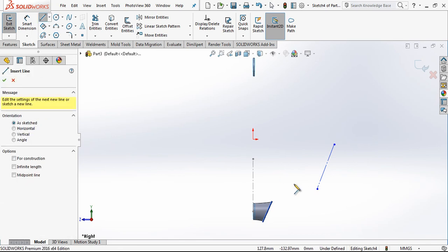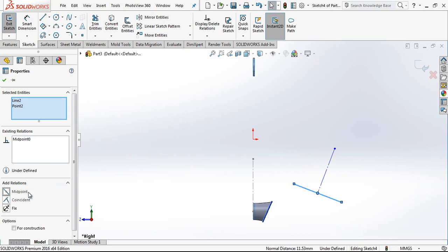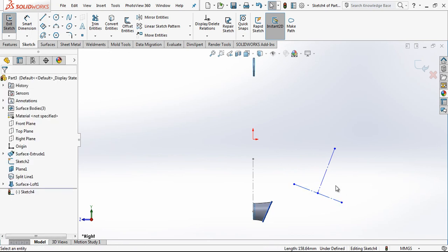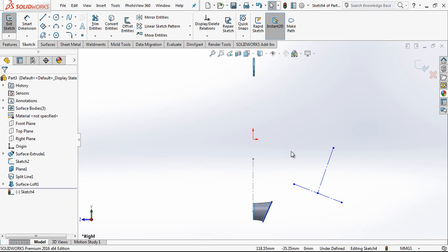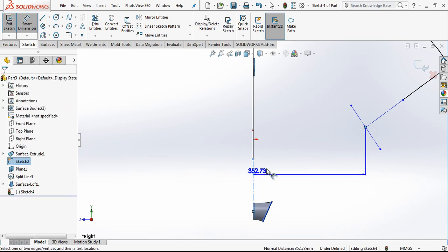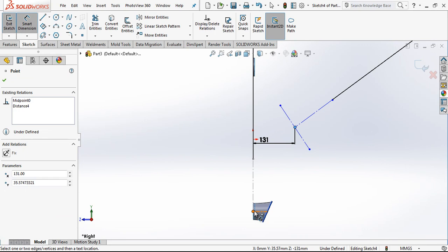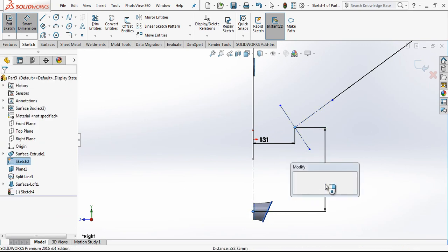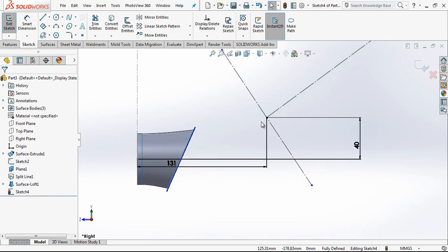For creating a plane, firstly of course we are creating a line for plane adjustment and the dimension and the position of the plane. This line is going to be 55 degrees, and this point to here 135.1. From the middle line to here it's 40. We create here a sketch.